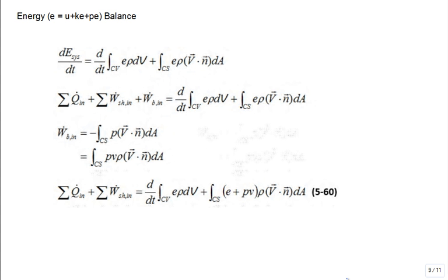Energy, I'm just trying to show you. This looks like the Reynolds transport theorem with energy being the property of interest, and we have specific energy. Well, how can energy come in or out of a closed system? Three ways that we studied. Heat transfer. Give me the sign convention. Q dot positive in. Great. Shaft work and boundary work. That system can be distorted.